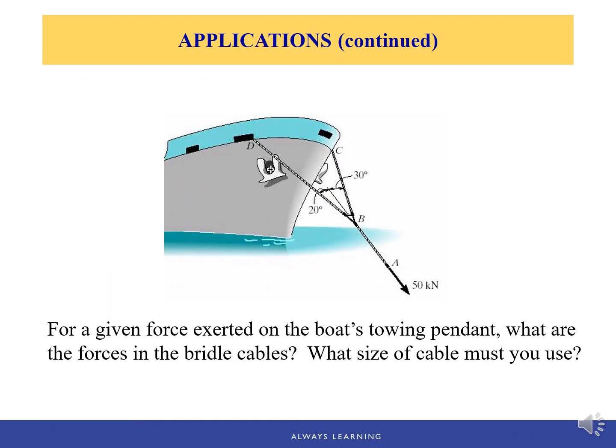Or in this example, we have one given force applied at cable AB or BA, and then we can find the force developed in cables BD and BC using equilibrium of a particle equations, and then further calculate the size of the cable based on the given material property of cables BD and BC.